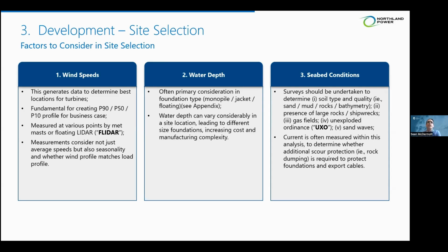In the renewable energy space, and particularly in the lender space, you'll hear reference to P90, P50, P10 as reference points. Not everyone knows what that means. So the P in front of the numbers refers to probability. And P90, P50, P10 looks to establish a baseline for, in any given year, how many hours of generation you are likely to have. So this is sometimes also referred to as the 8760 analysis, 8760 or 8,760 being the number of hours in a year.